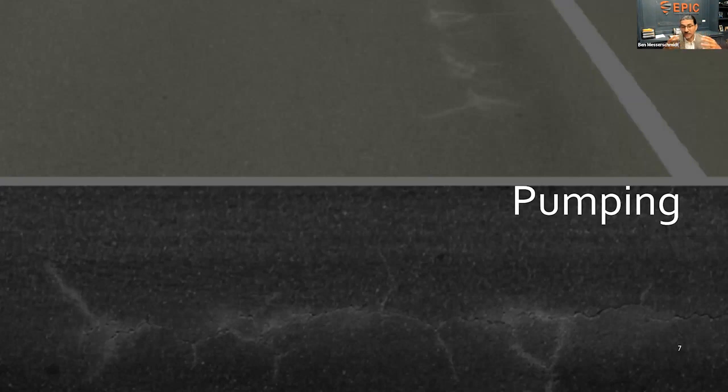Now, the path of least resistance, if you have some large scale cracks within the pavement surface, is going to be to breathe through the pavement, as opposed to going out through the densely packed earth on the outside. So water, moisture vapor is always going to find the path of least resistance coming up.